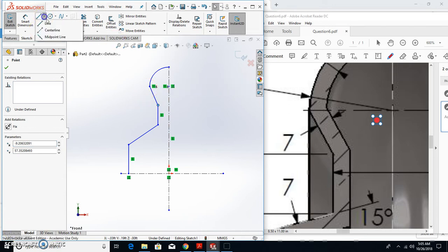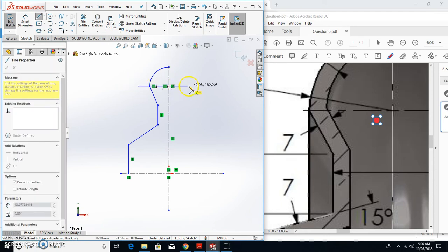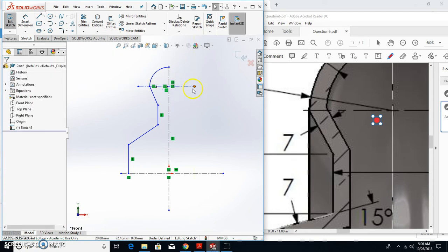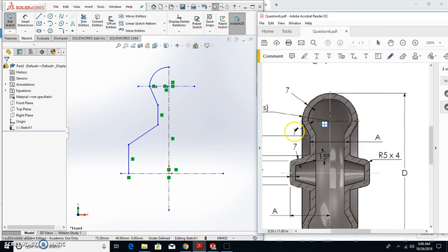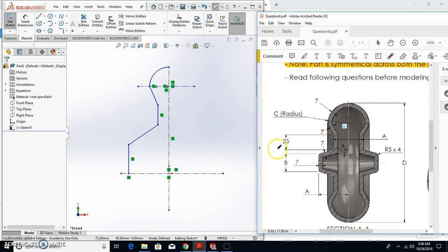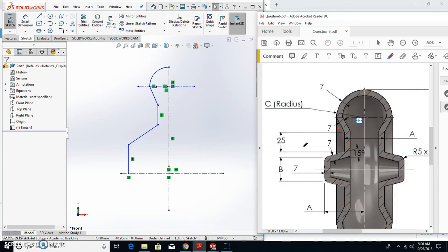Okay, just for reference, I'm going to put a horizontal reference line in here, so you can see that. All right. So as I come over here and scroll back out, you can see all the dimensions. So I'm going to start dimensioning my part. Now the cool thing is, as I dimension over, since we're doing a quarter of the part, SolidWorks is intuitive enough to know that you put these center lines in here and you can push those dimensions out to be diameters instead of radiuses.